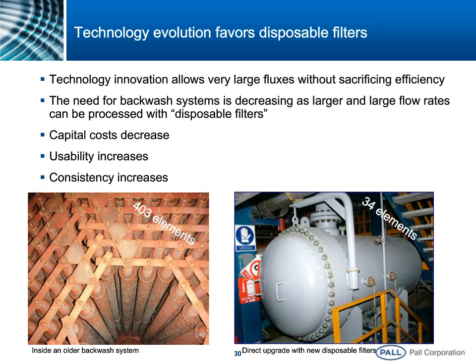amounts of contamination. Just one last note, look at the color of the elements on the left picture. Obviously, who is to deny the fact that iron particles, rust, are really the challenging contaminants in this system? I mean, they're coating everything inside the system. So again, iron, about 95% of our problem in these systems.